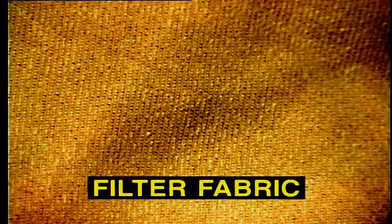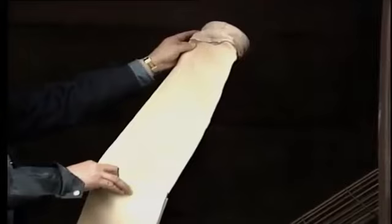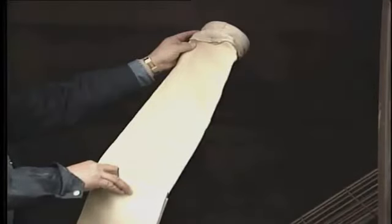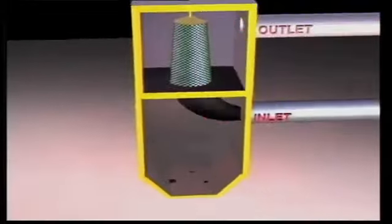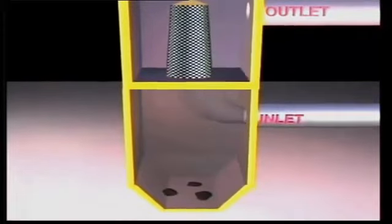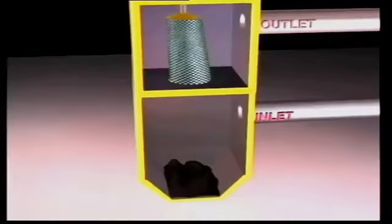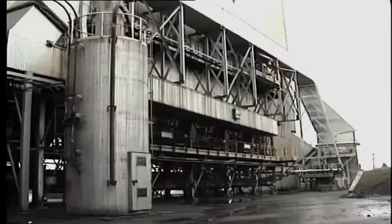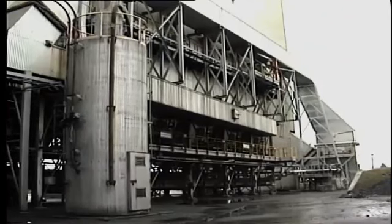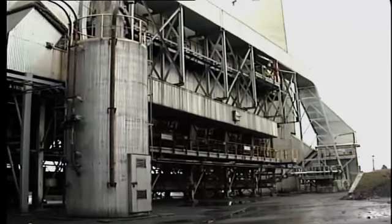Actually, it is not so much the fabric itself which blocks the passage of particulates, rather it is the layer of ash cake which builds up on the surface. The filter material is arranged in the form of a very large number of long bags, which are replaceable. The inlet gas flows upwards on the inside of the bag and passes through the fabric. As the inside of the bag becomes plugged, the pressure drop increases and the bag is cleaned by mechanical shakers. Means are provided to isolate sections of the filter so as to provide cleaning of some bags while the remainder of the filter continues in service.